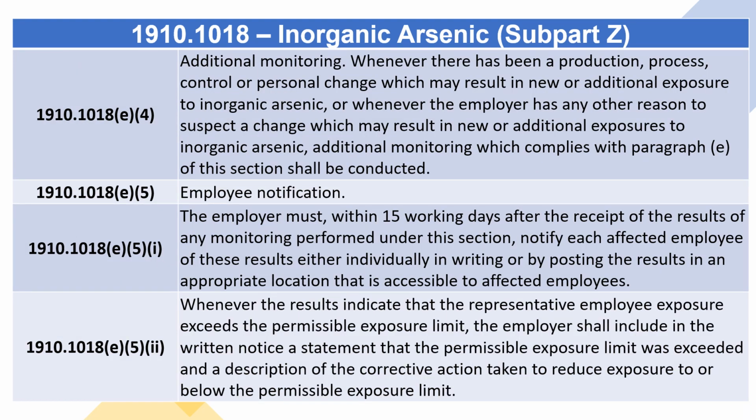1910.1018(e)(4) Additional monitoring. Whenever there has been a production, process, control or personnel change which may result in new or additional exposure to inorganic arsenic, or whenever the employer has any other reason to suspect a change which may result in new or additional exposures to inorganic arsenic, additional monitoring which complies with paragraph (e) of this section shall be conducted.